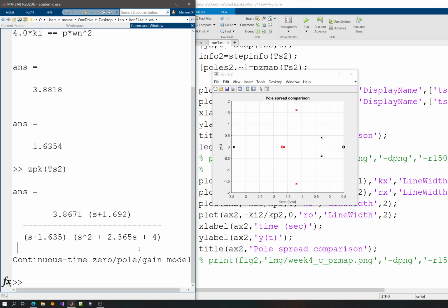And the dominant pole placement is a solution, but this reducing degree is a better solution in terms of approximation of the system response. In dominant pole placement, you have fast poles, you have the same degree, but in pole zero cancellation, you are reducing the degree, so it becomes more like a second order system.